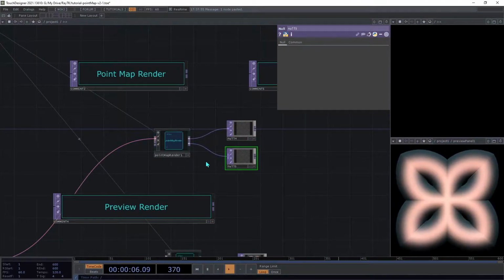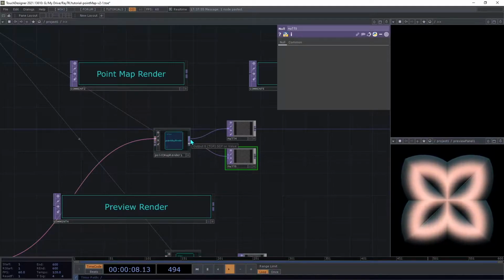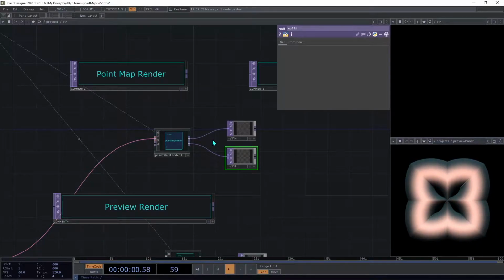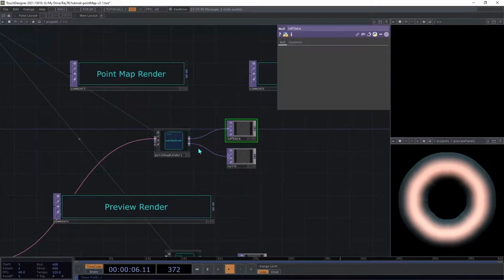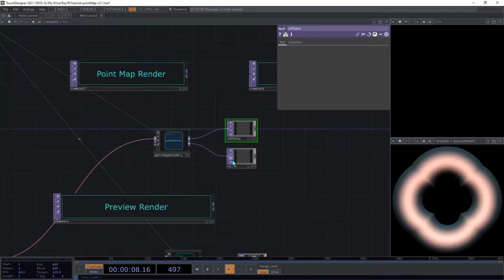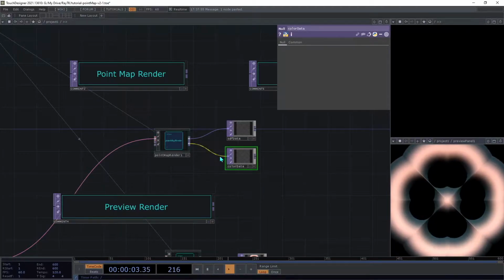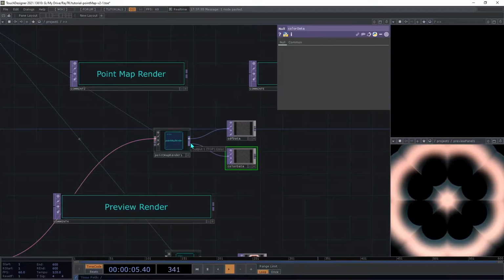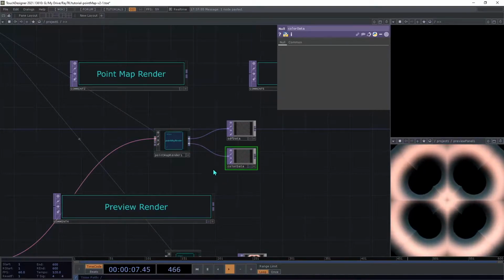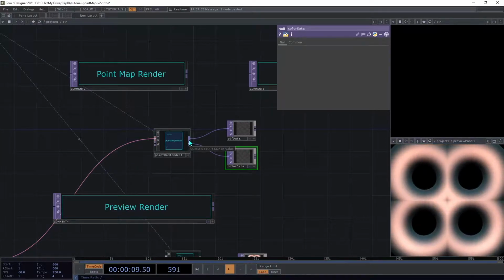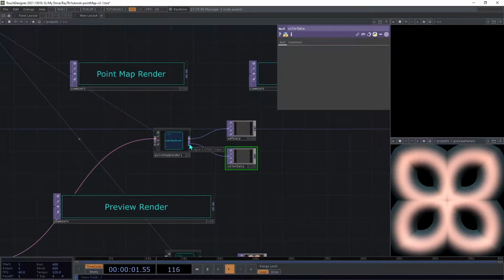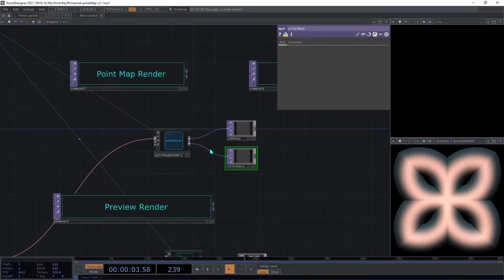For the output that has the label SDF or value, we're going to name the one connected to that SDF data. And the other one that's color, I'm going to call color data. Now the ordering of these two outputs has changed in this release of the toolkit, so just make sure you're paying attention to the label when you mouse over and connecting them to the right thing.